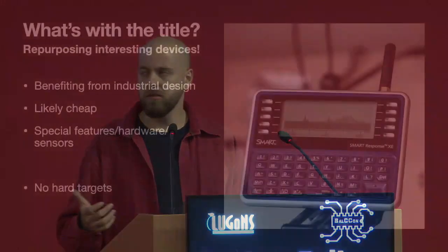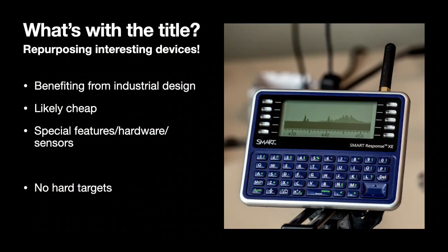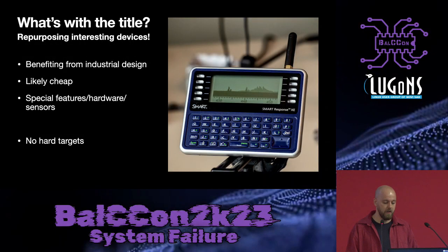And this thing in the photo is called Smart Response XE, which was an exam taking tool. I guess it looks like a calculator, but it's not. You can answer questions on it on an exam and stuff like that. But somebody figured out that it's pretty much Arduino compatible. You can flash your own firmware on it and make it do something interesting. So I took it and made it into a spectrum analyzer. There's an antenna on the back, and you can repurpose the whole device, use the existing keyboard, use the existing display, and make it do something fun.